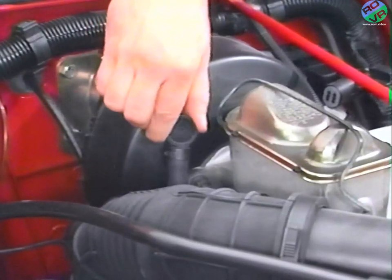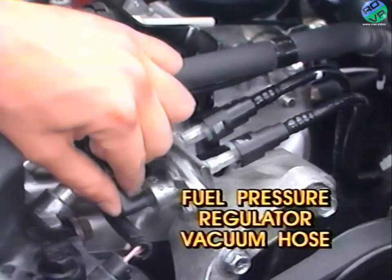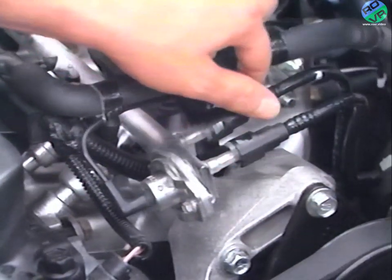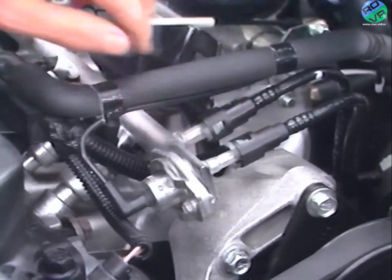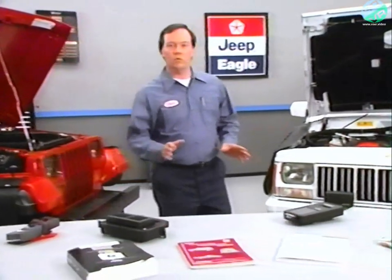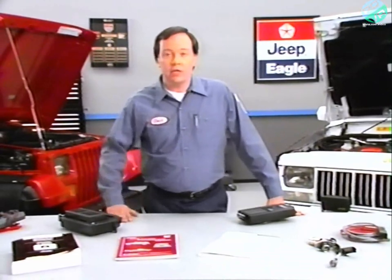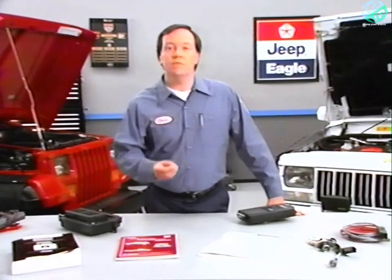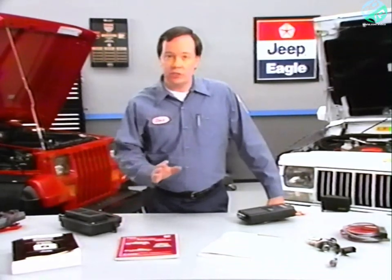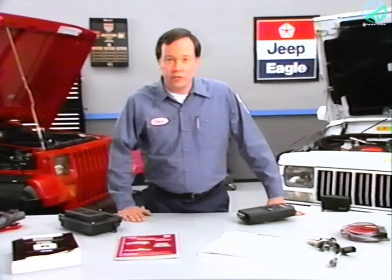Also check vacuum lines, such as the brake vacuum booster hose and the fuel pressure regulator vacuum hose. It's also important to check for fuel leaks at the quick connect fuel rail connections and at all other fuel lines. That was just a brief sampling of things to check for while performing a visual inspection. The 1991 Engine, Chassis, and Body Service Manual and the Helpful Information section of the 1991 Powertrain Diagnostic Manual each contain a list of the electrical connectors, vacuum, and fuel lines that should be checked.